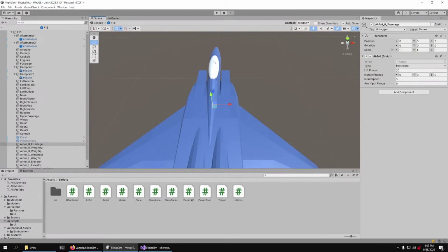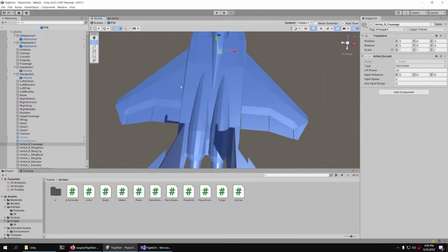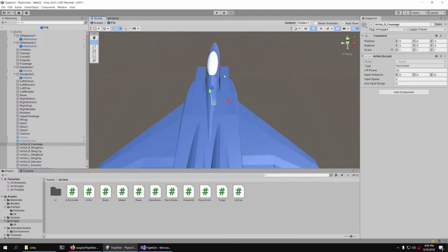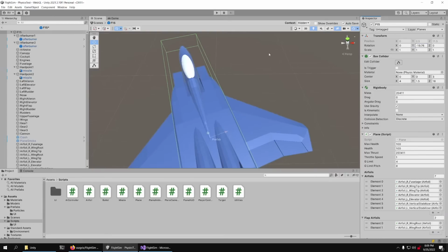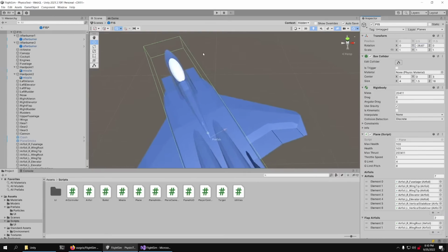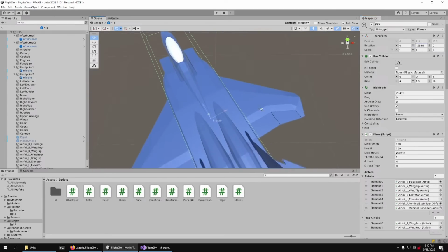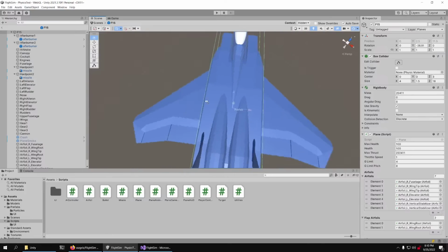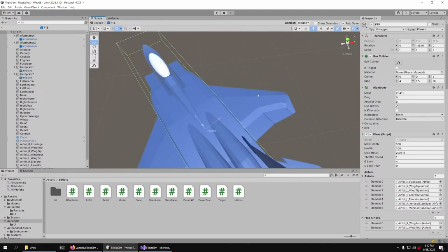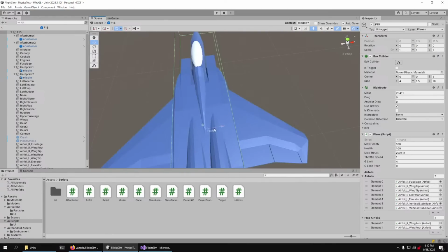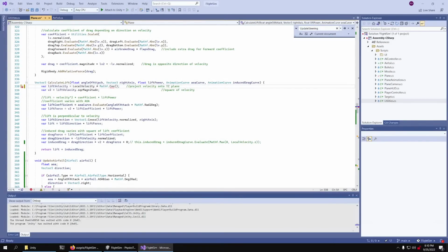And note that your angle of attack yaw also affects how the wing sweep goes. Whenever you yaw, for example, if you yaw like 20 degrees to the left here, that means your right wing is now flat on into the wind and generates more lift, and your left wing generates less lift, and that causes your plane to roll to the left. So to do that, we actually need to pass angle of attack yaw into this function.